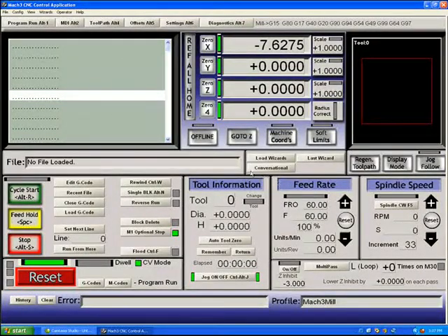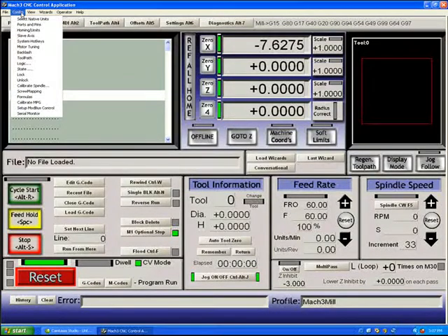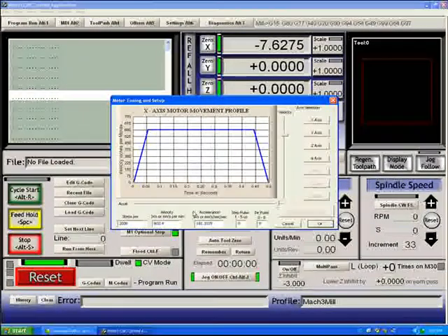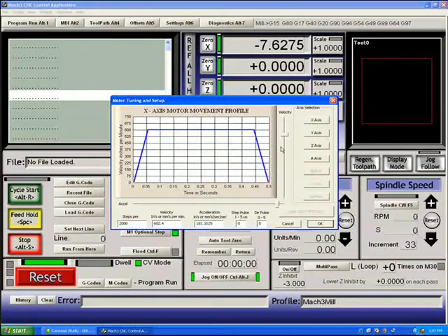So now we have set up our motors and we want to move down. The next step that you need to do to get basic movement is motor tuning. So we'll go to the motor tuning stage. The first thing that's important is how many steps per unit it takes to move your table. As I said earlier, we set ourselves up for this machine in millimeters, so the steps per here refers to millimeters. Steps per millimeter, I have mine set to 2,000.